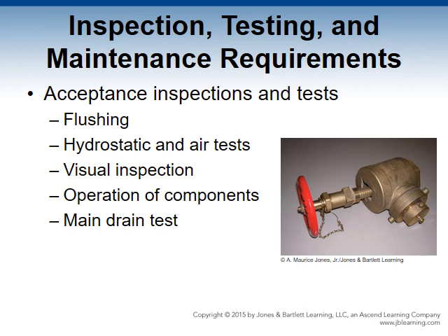For many components, this step only requires the following action. Operate a valve to verify movement of water through the system. Manually moving a component to make sure it has free range of movement, and observing that a device functions as performed and as design required.